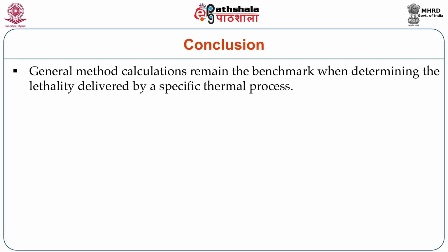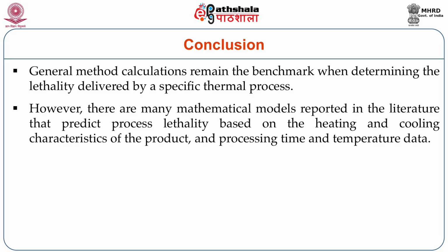Now, general method calculations remain the benchmark when determining the lethality delivered by any specific thermal process through various methods of heat transfer. However, there are many mathematical models reported in the literature which predict the process lethality based on heating, the modes of heat transfer, the cooling characteristics of the product and also the processing time and temperature data.